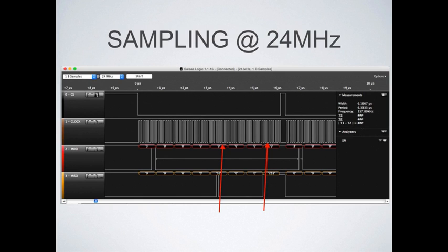You see the clock is going over the data sections, and there are a lot of gaps in the clock up there. There are wider black waveforms in some sections. That tells me that I'm probably not clocking fast enough to collect data correctly. So I need a better logic analyzer. One of two things you can do: go back into the code and modify it, as I did, or buy a better logic analyzer.